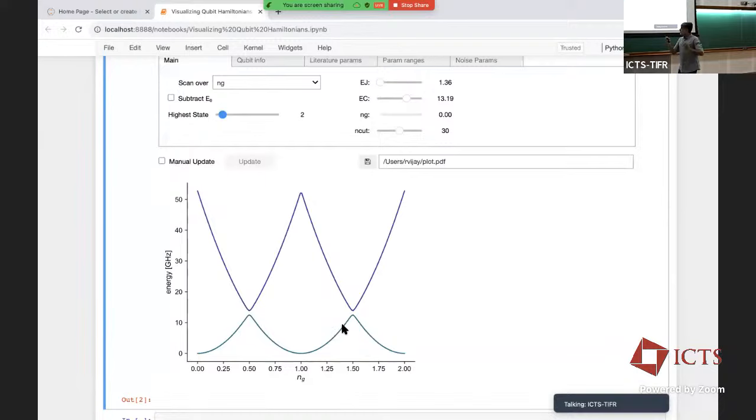For those who have maybe never heard this, it turns out that when you make things on substrates, there are always charges jiggling around in your neighborhood. And these act like a noisy gate voltage on your device. And it turns out there's nothing we can do about it. So people saw this, they knew about this, they saw that this was very bad. The first thing that was done was to move to these so-called special points, which are called sweet spots, where they become first order insensitive, and you can directly see that your decoherence times improve, especially the dephasing time, significantly at this particular point.